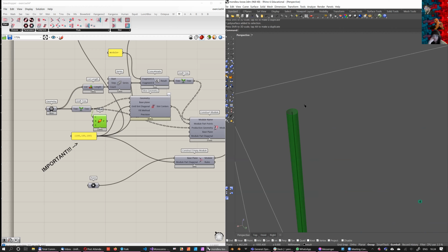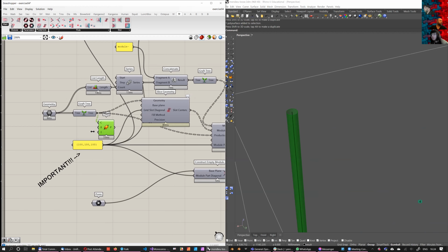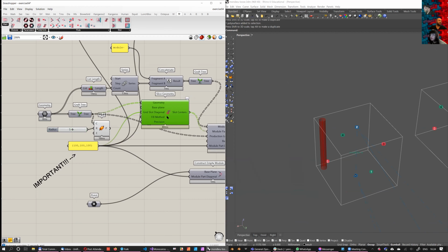A sphere doesn't have naked edges, a donut doesn't have naked edges, a cube doesn't have naked edges, but if you just delete one side of a cube, there is a naked edge. So this is, let's make the radius a little bit bigger, like 5 units, so that we see it better. So this is a B-rep.